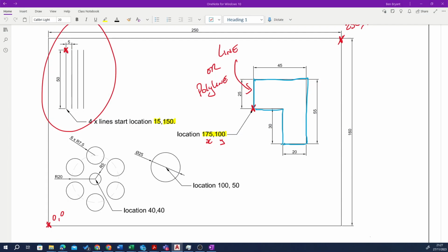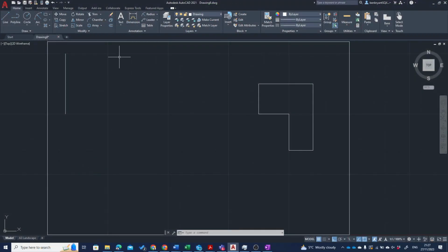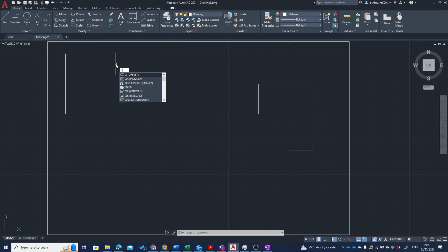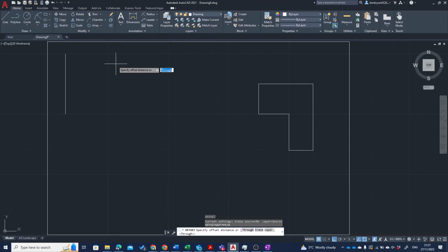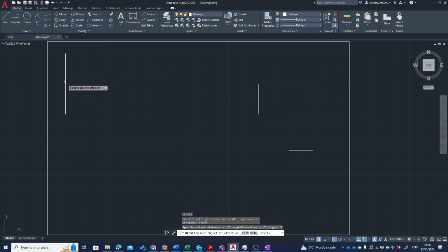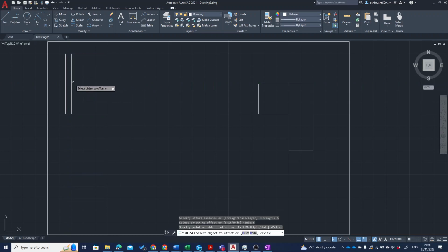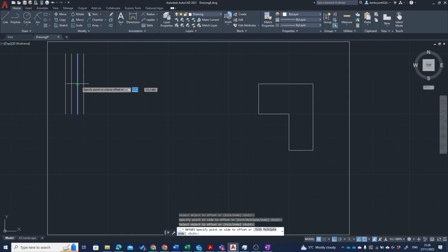You'll notice that actually we have an offset here of 5. So I'm going to offset this tool. So offset lives here, or O is the command. If you type it in, I want 5 mil of offset, which is my distance, and I click once, move my mouse to the right, click, reselection box comes up, click again, move over, click, one final time, click.